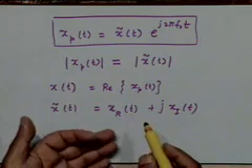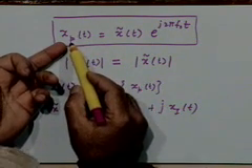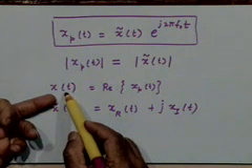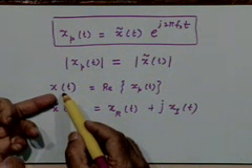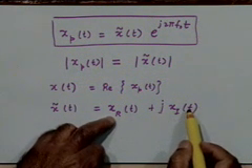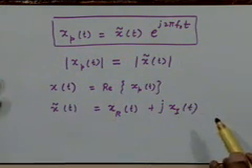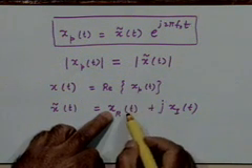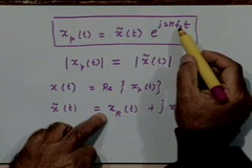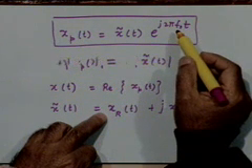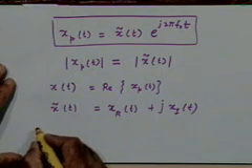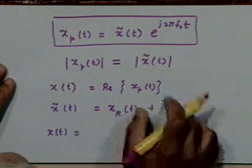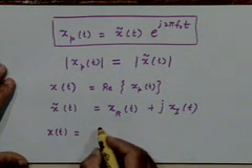And just like I have a representation of x_p(t) in terms of x tilde(t), what I would like to find out is whether there is a corresponding representation of the original bandpass signal in terms of these components. It's very simple. All you have to do is substitute for x_p(t) into e to the power j 2 pi f naught t and take the real part of that. So what will you get? We will get x of t. What will be the real part of this multiplied with e to the power j 2 pi f naught t?